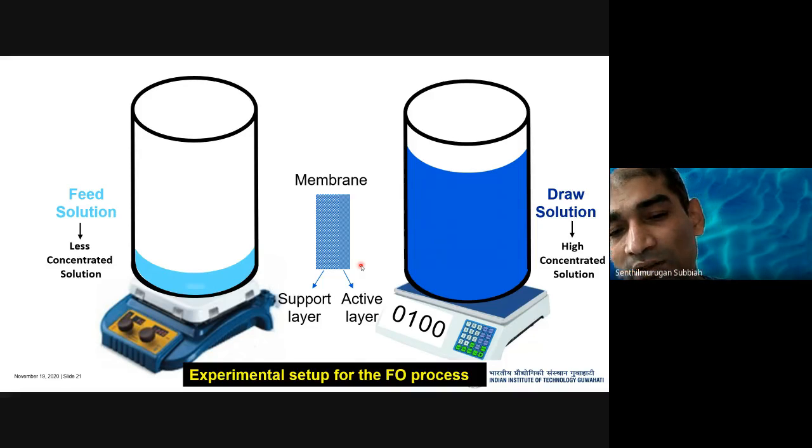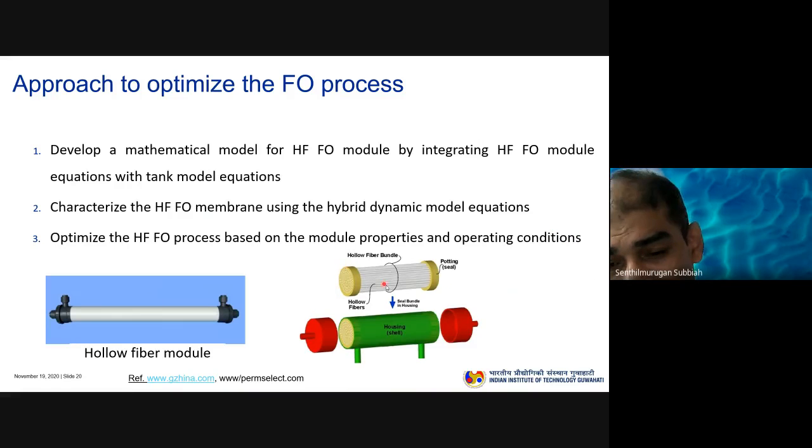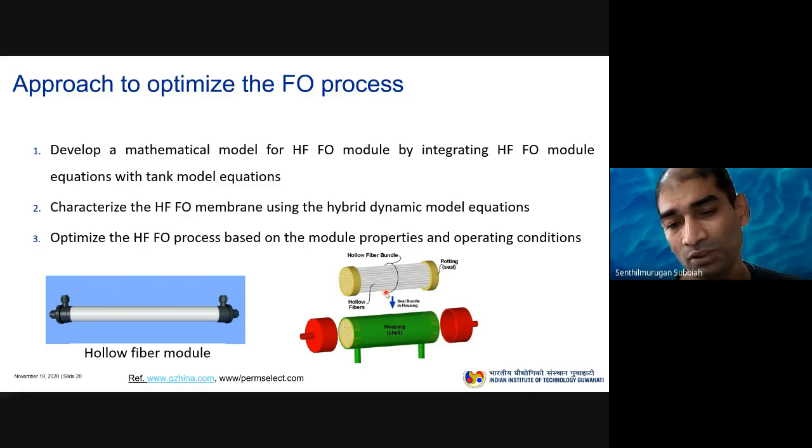Another aspect, if you talk about the hollow fiber module. When we say hollow fiber module, these fibers are assembled in such a way that the fibers are very small, and if you pass, let's say, highly fouled content, the fouled content can choke the fiber lumen side. That's why we prefer that the low fouling content be passed through the fiber lumen side, and the high fouling content be passed outside the fiber. So this is one way of making a process fouling trouble free.